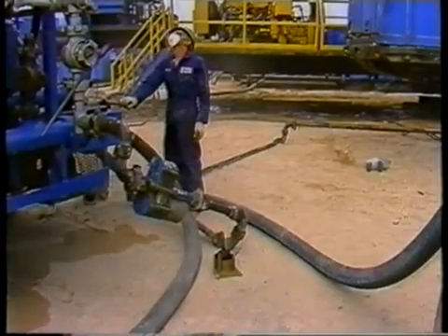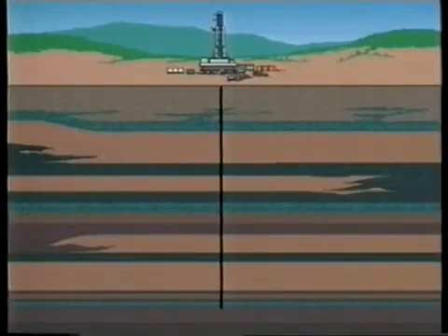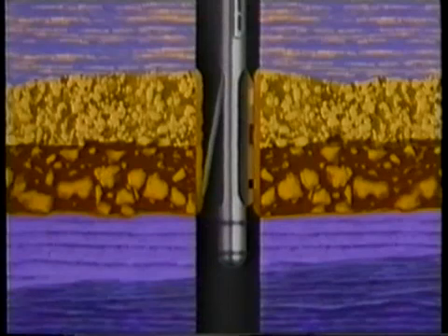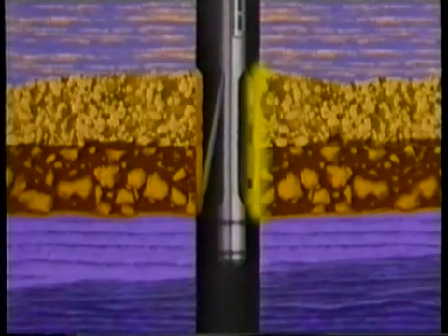The main reason for cementing the casing in a well is to isolate and control the fluids and pressures present in subsurface formations. Unfortunately, while accomplishing these goals, a casing string also permanently prevents us from evaluating those same formations using many of the techniques employed by open-hole logging tools which can be placed against the wellbore wall. So, if we want to monitor changes in reservoir fluid saturations over time, we need cased hole logging tools which can see through the casing and cement barriers we've installed.